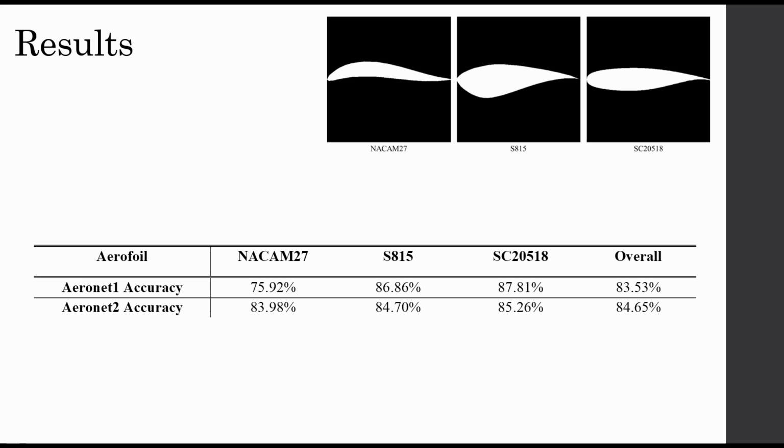So, once the models have been trained, you can simply feed new airfoil geometries in with flow conditions, and the models can make predictions for the force coefficients. On average, the networks take less than 10 milliseconds to make a single prediction. When compared to the 270 seconds to run a single one of the CFD simulations, the potential time savings are clear to see. I gathered more CFD data on some airfoils that the neural network had not been trained on.